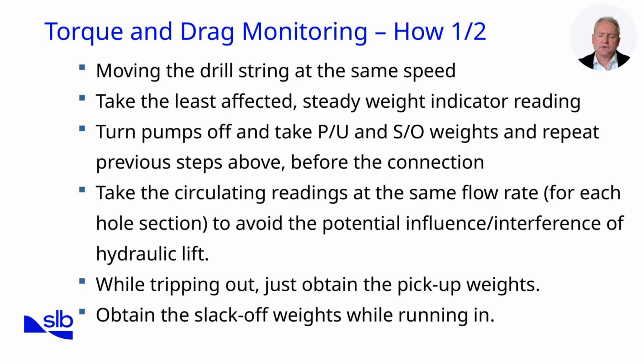First, when moving the drill string, it should be done at a constant speed. Pick-up and slack-off movements should each be 15 to 20 feet in length, as short movements can be distorted by elastic stretch or mechanical lag.